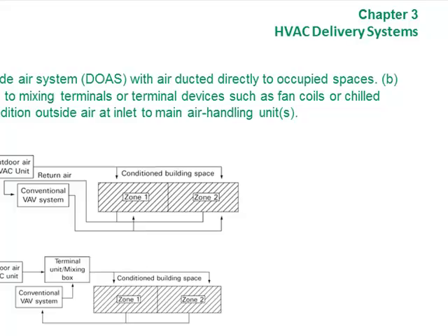Who does all the heating energy and cost evaluations, to consider the kind of insulation the building's going to have, what kind of building it is? Who does that, after you build it or before you build it? It's in the process. The engineers and the architects all work together, because the architects will spec the insulation in the building materials, and the engineer needs to know that so they can know the R values of the walls and the U values and all that stuff, and design the most economical system within that. So you kind of work together through the whole thing.